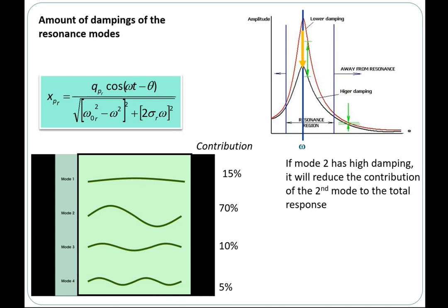So here you see that, I mean, here we are not talking about the force itself yet. It's talking about the resistant parts. So if you want to know why your machines vibrate like this, why your machines vibrate like that, then here we are saying that you need to know the dynamics of that particular machine. So here is referring to its natural frequency, damping, and its mode shapes. Then from there, you know that at this particular case, okay, it is a resonant case.